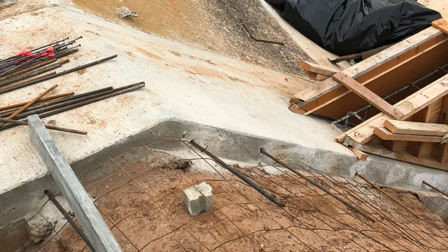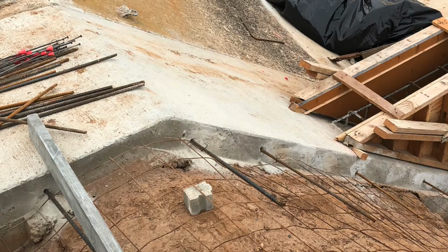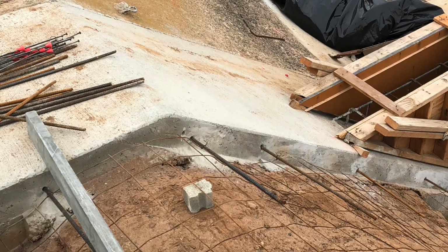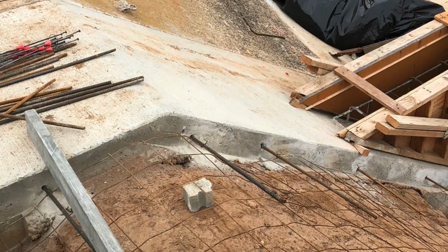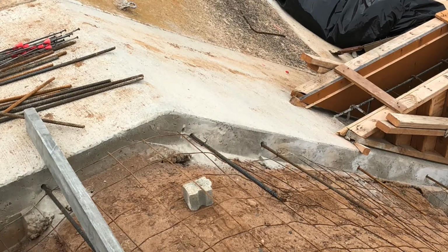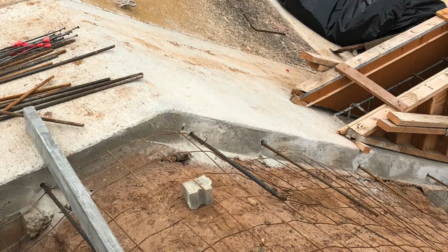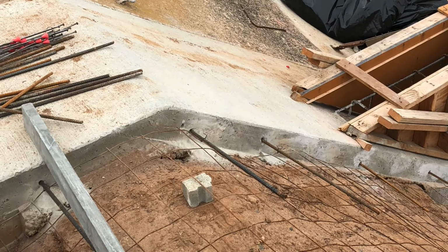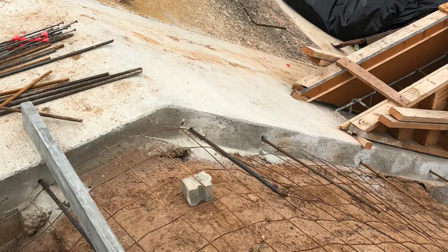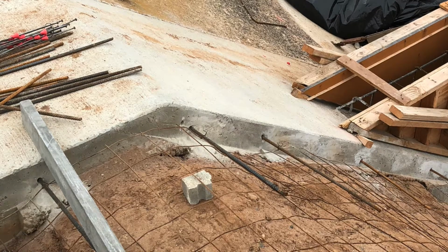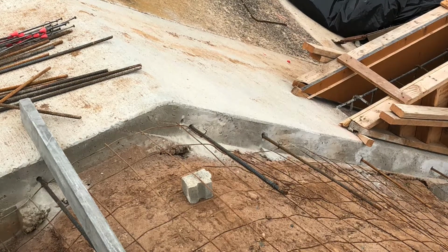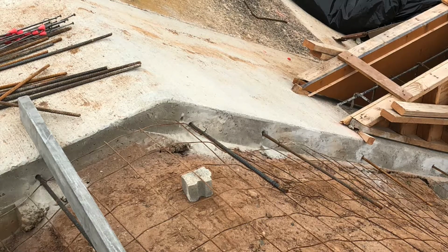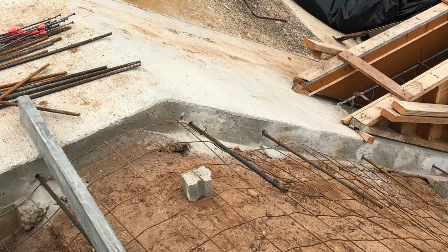Next, I did want to use this as a quick reminder. If you are dealing with any sort of sidewalk or concrete pavement, typically if you're joining it together with the existing pavement or with future pavement, you have to place what are called dowels. And dowels are basically sticks of rebar that stick out from the side, as you can see in front of you. This connects the two pieces of concrete, the existing and the future, with rebar to absorb some of that stress and tension.